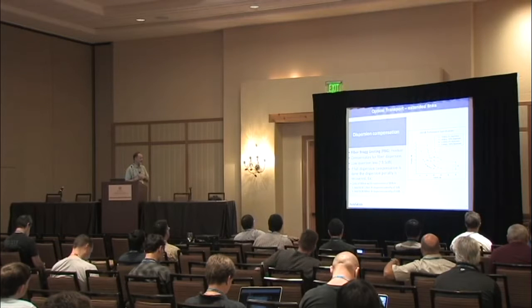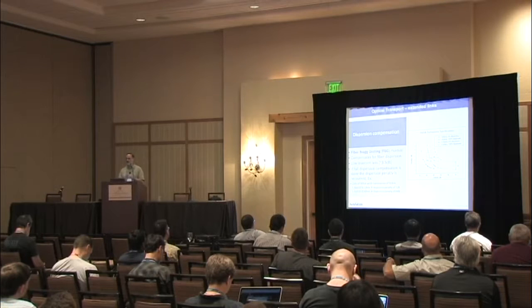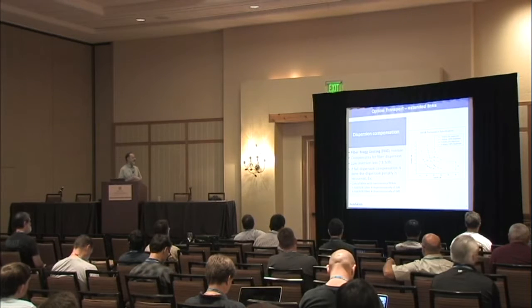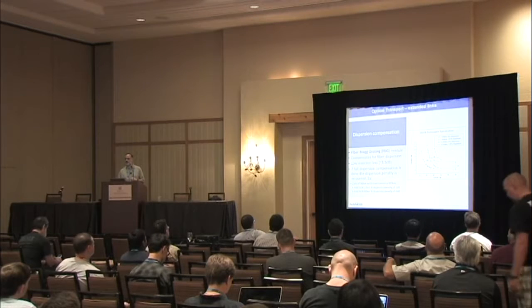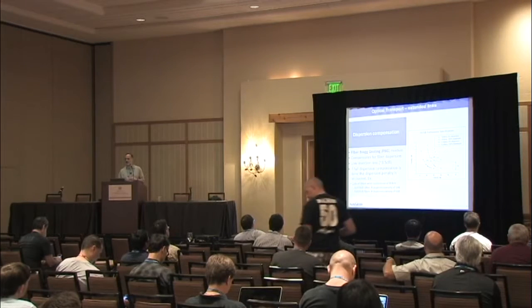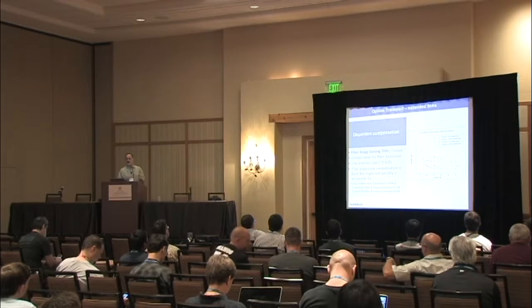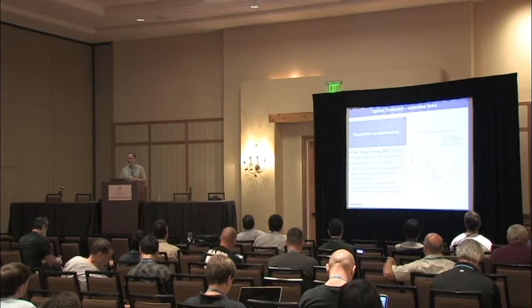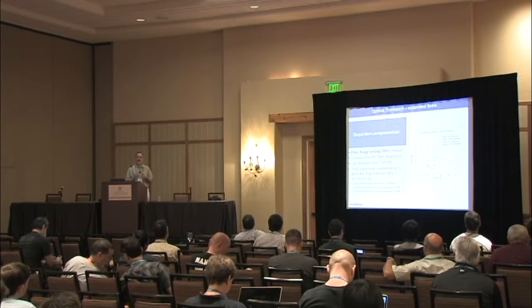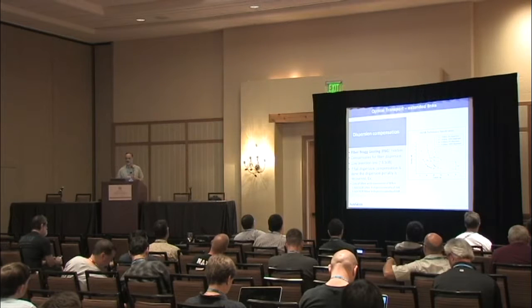So I have an example here. You have a link of 90 kilometers with a transceiver of 80 kilometers, and we are going to talk in kilometers, even if we should talk in ps per nanometer. But if you had a DCM of 10 kilometers, you're going to still pay the 3 dB penalty that we mentioned before. If you had a DCM for 90 kilometers, you recover those. Your dispersion penalty is going to be 0. So if you need those 3 dB, that's a good way to recover. And again, that's good for 10 and 40 gig; 100 gig is a different story. 100 gig coherent optics dislike dispersion compensation.